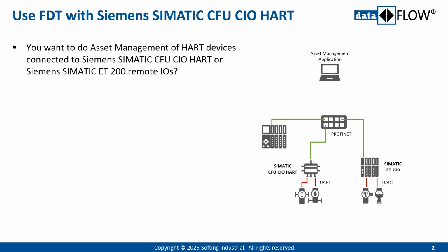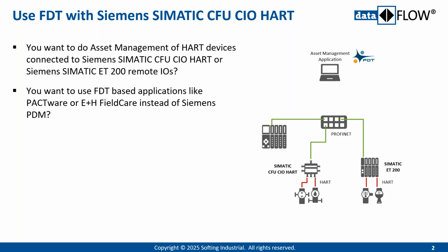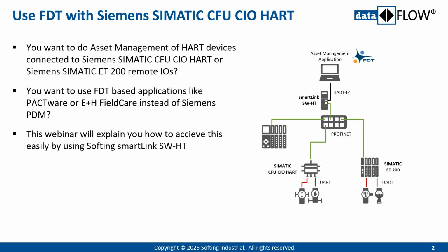Now the problem we want to address here in the webinar is this: you have an asset management application you're connecting to. The special thing is that you want to use an FDT-based asset management application like PACTware or Endress+Hauser FieldCare, and not the standard asset management application from Siemens, the PDM. In the webinar, we will show you the solution, which is bringing these two parts together.